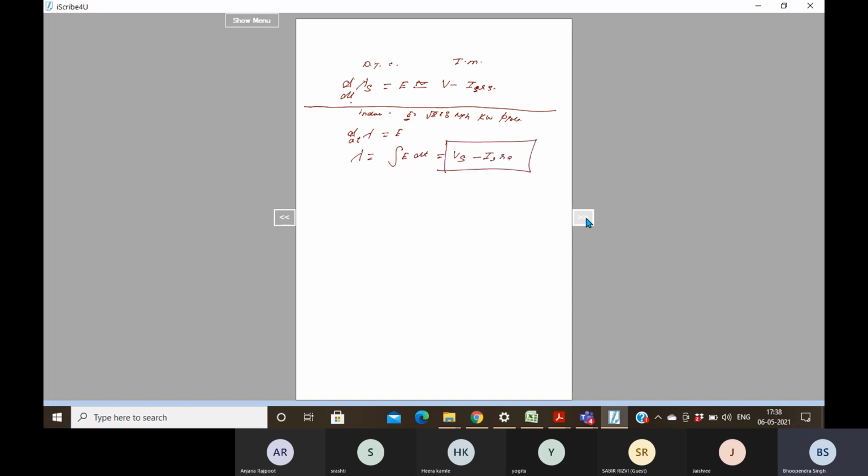Remember the meaning of these parameters. This is Vs, the space vector. Now, what is the space vector? Va, Vb, Vc in the natural reference frame, converted to V alpha, V beta in the two-axis stationary frame. And V alpha and V beta can be converted to a vector V at some angle theta. So this is your space vector.